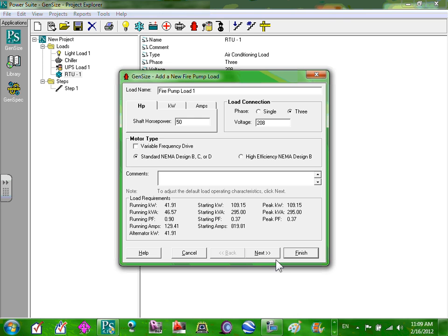The other thing, in addition to the 15% voltage dip limit, is you can't really put any voltage reduction and take that into consideration. For instance, an auto transformer. You can have it on the thing, but you have to size it as if it's starting across the line. Okay? Couple of quirks with fire pumps.